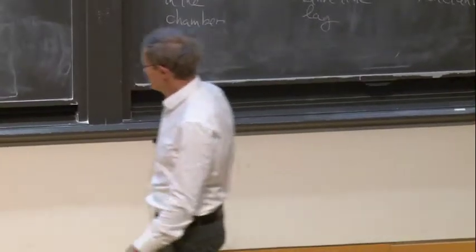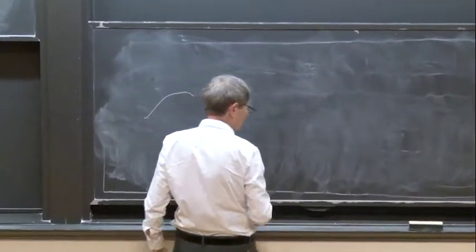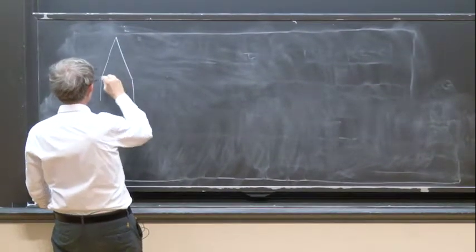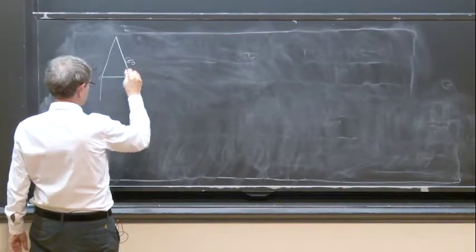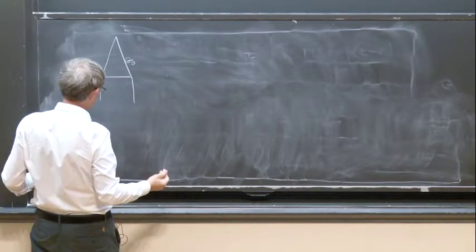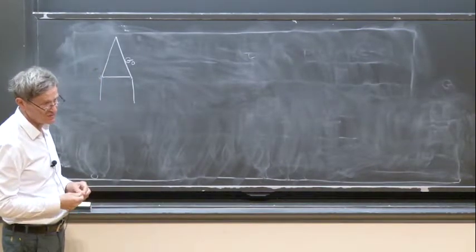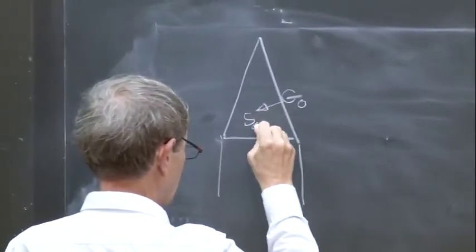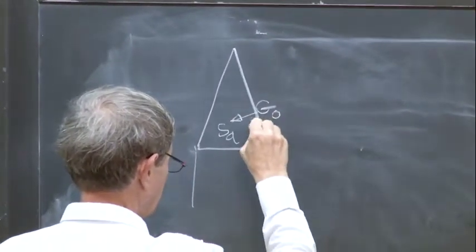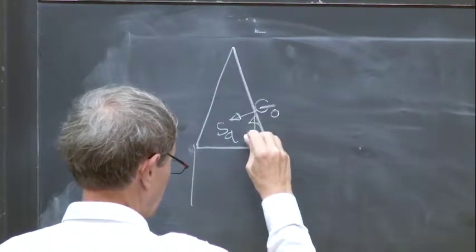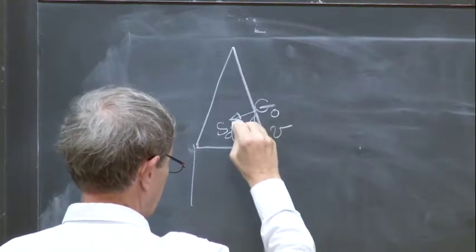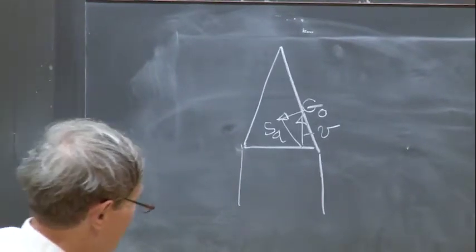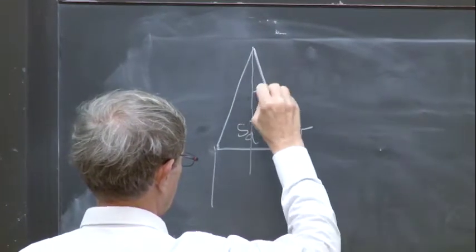You have a flame which is here. This is, for example, a steady flame. What is a steady flame? For example, you have this conical flame. This is steady. G0 is right here. What is the surface itself? It's a cone, and how is the cone formed? On one side you have the displacement in the normal direction. On the other side you have the velocity of the incoming fresh reactants, V. And you need to have something like that. This triangle will define the cone. You will have alpha 0 here.